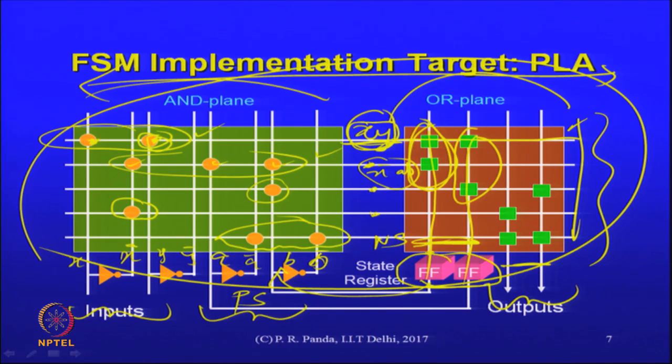What do you mean by optimize? Whether you optimize the number of columns more or the number of rows more, that is where the balance will come in. Yes, we should understand the trade-offs here. Some of the choices are interlinked. For example, the number of state bits by itself does not say much, but it depends on how you are actually doing the encoding. It is possible that for some choices of length of the state register, the logic is simpler. You actually might need fewer product terms. Then, since we want to optimize the product of the columns with the rows, there is some such uncertainty.